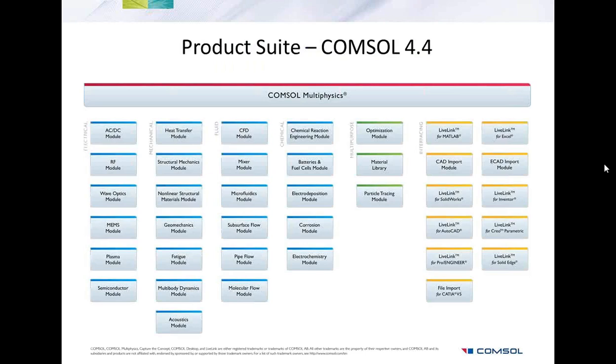Yes, but I wouldn't suggest using the model that I just demonstrated where you actually model the bubbles themselves. COMSOL has some bubbly flow models which simplify the modeling process, and they use a volume fraction of air to water ratio, because as you can imagine in those sorts of effluent plants, there's a massive amount of bubbling and processing that it would just be computationally too excessive to model as individual bubbles.